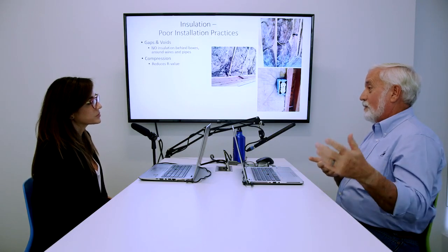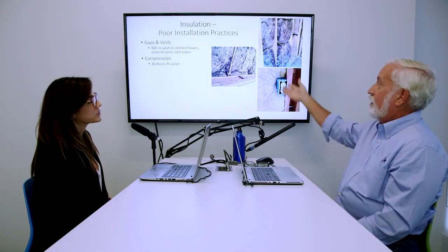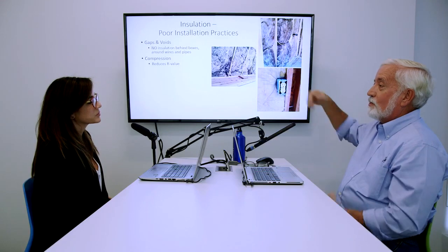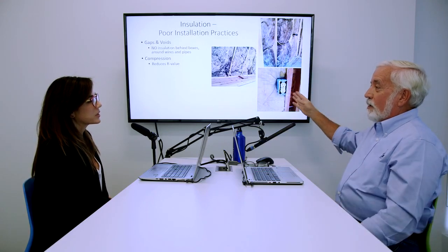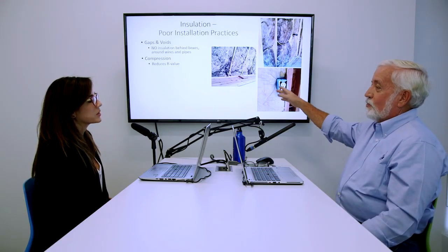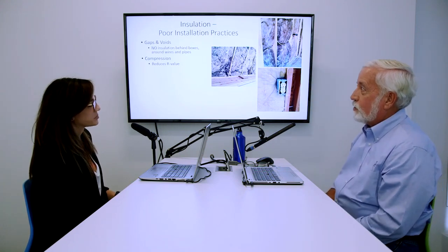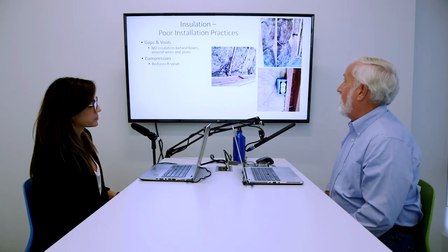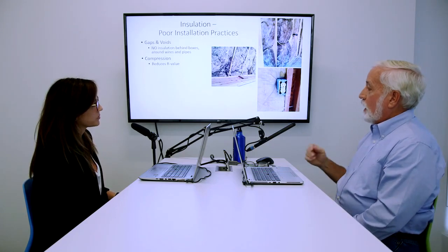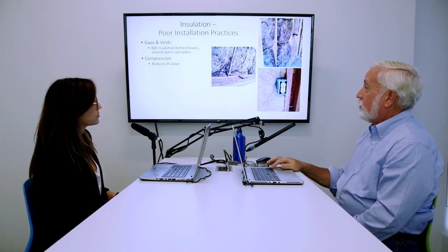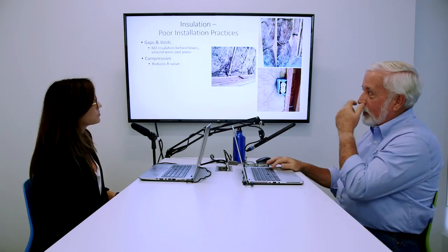Which, when we think back about the wall insulation where they blew the insulation in with a net and blow, that's perfect for every one of these. Because why? Because it's full. It automatically conforms to the boxes, to the wires, to everything. It gets all the gaps. We don't have any compression. We don't have any reduced R value. We don't have any air pockets. And we have a quality installation. And it's an effective insulation.